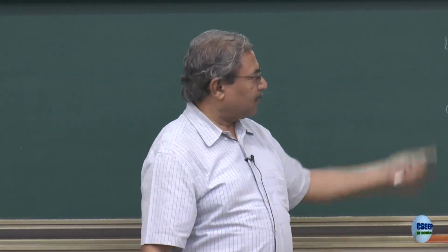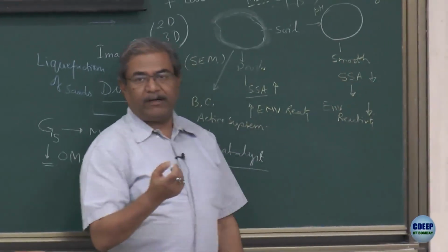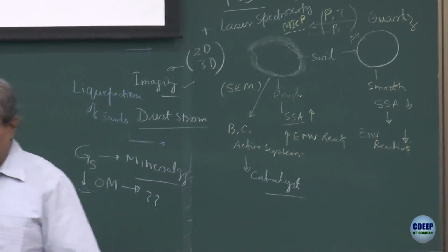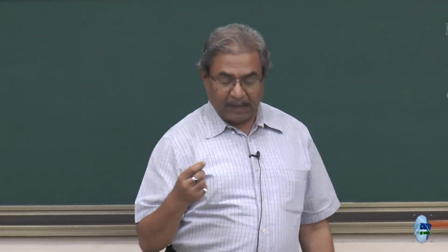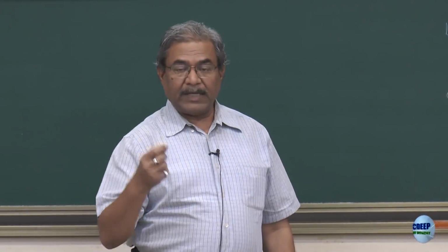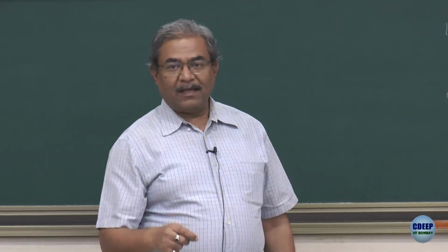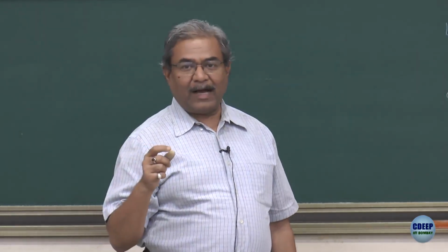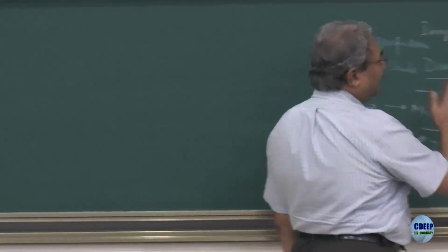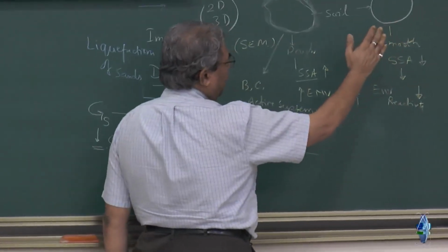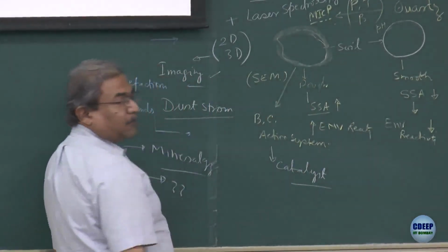Surface area, I talked about the surface area. So, total area divided by per unit weight of the soil mass is specific surface area. And this again becomes a very critical parameter in environmental geotechnology, because when you are selecting the material for your specific applications, unless the specific surface area is very high, I will not use it as a catalyst. Then this goes in the reclamation. If surface area is very high, chemically active material, I can use it for some other industrial processes.